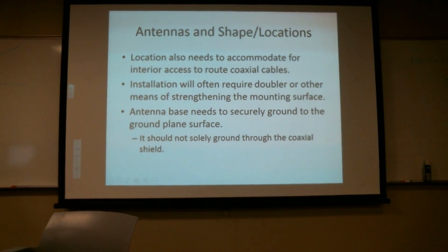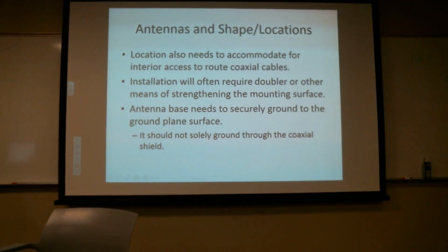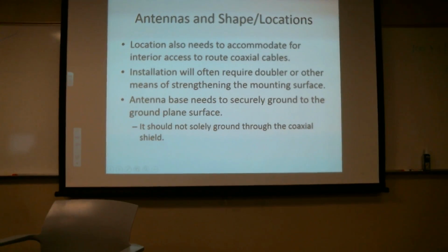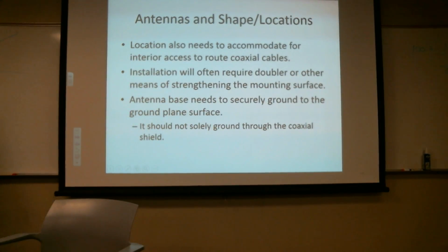Now the GPS antenna, or even cell phone antennas, the reason you don't see much of a ground plane is there's such a high frequency, the ground plane is like that long. So it's part of the antenna assembly. In fact, that's why they make a little hockey puck. The antenna sits in the middle, the ground plane sits out here, the antenna actually sort of runs in a little racetrack, and then in the middle, there's a computer that's doing a whole bunch of processing and amplifying and sending the data down the cable, or up the cable, depending on which way. Okay.